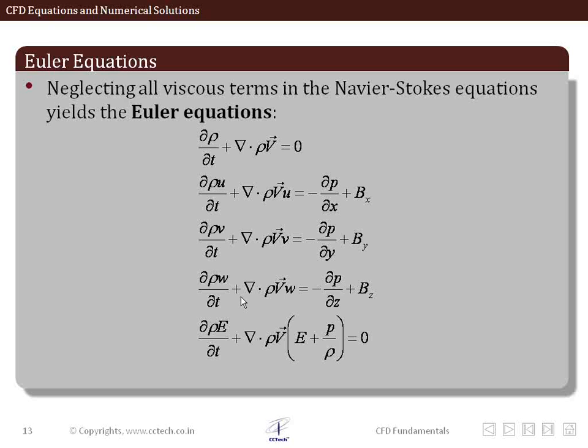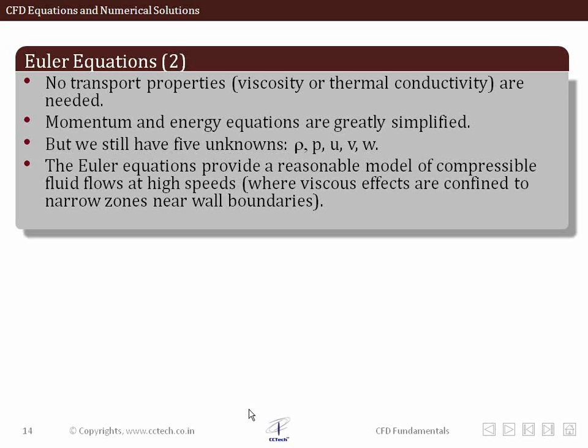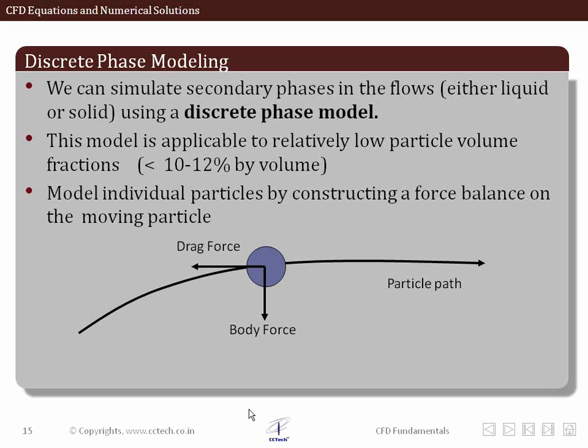When I say inviscid, there is no viscosity. But that also has some implications on the energy equation. You can see here in the energy equation there is no conduction term included. So we are not having viscosity or thermal conductivity. So it's quite simplified and we can easily solve such problems, and this has been used for a long time for designing flight simulators and panel code methods for ship simulations.